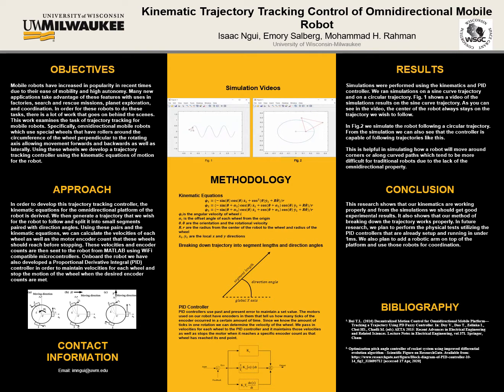So we tell our motors we want them to move at a certain RPM, rotations per minute, and then what the PID controller does is it looks at the error and the current speed of the motor, and it'll try and bump it up and force it to maintain the specific velocity we want. So we basically tell each wheel we want it to go to that velocity and maintain it,